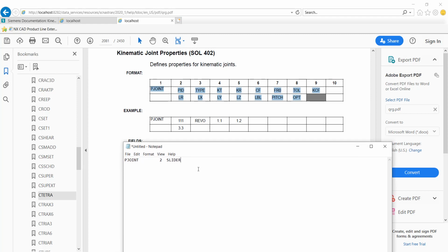replace. For example, we are just going to keep using the standard small field format for writing the syntax. That is to say, every 8 spaces will represent one field. For example, if I count from left to right, 1, 2, 3, 4, 5, 6, 7, 8, this will be one field, referring to field number 1.